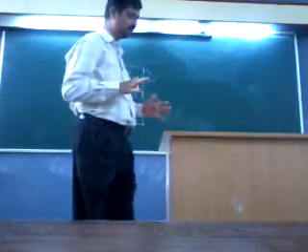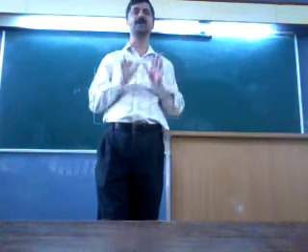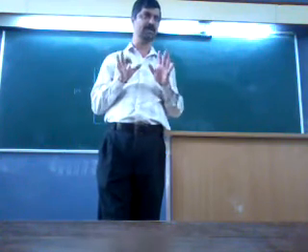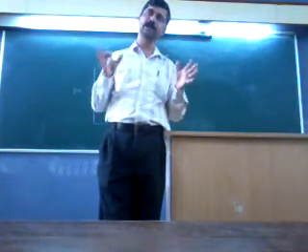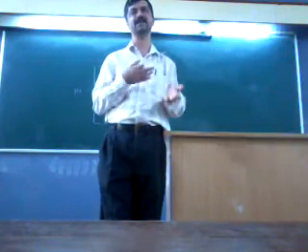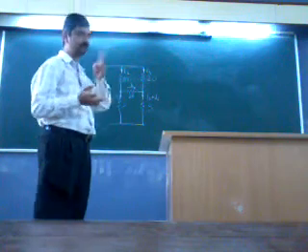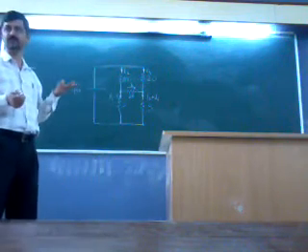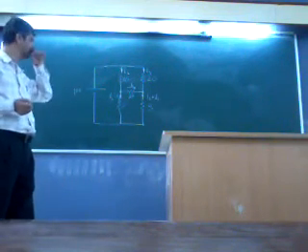The first thing is that when there are 5 arms, there will be 5 currents. So I1, I2, I3, I4, I5 you can assume, and then you can apply Kirchhoff's laws to express one in terms of the other, which both of these steps we have applied at once here.